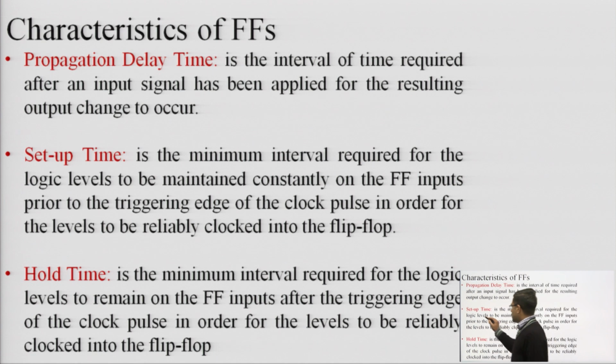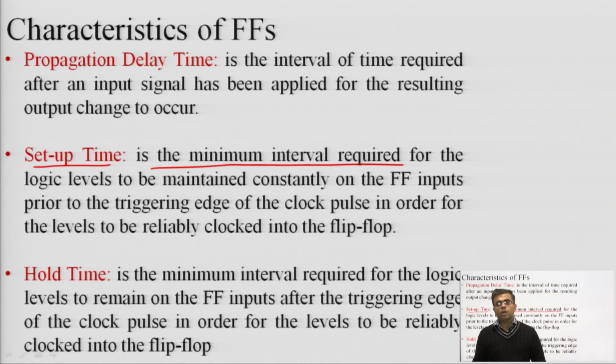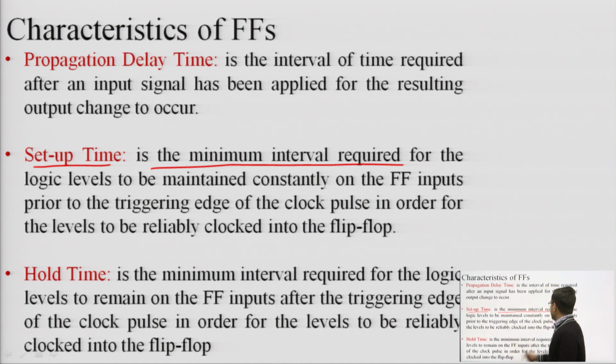Then setup time. As the name suggests, it is some kind of time which is required before the actual thing, for setting up something. It is the minimum time interval required for the logic levels to be maintained constantly on the flip flop inputs. That means it is the time before the application of the input, which is why it is termed setup time. Propagation delay was after the input has entered the circuit, and whatever time the circuit takes for processing is the propagation delay, but the setup time is the time before the application of the inputs, a minimum interval for the logic levels to be maintained constantly on the flip flop input.